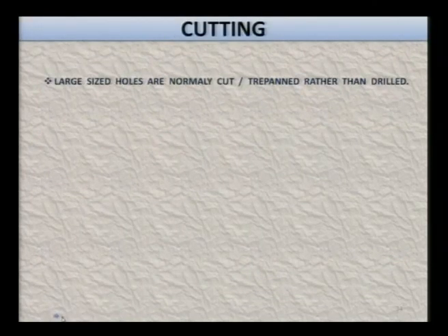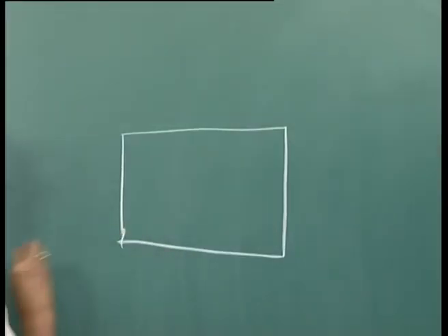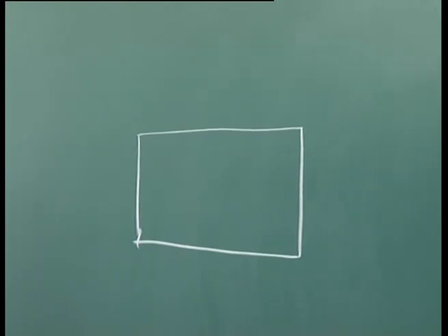Then there are various applications as long as cutting is concerned. Large sized holes are normally cut rather than drilled. This is a very important point. I will just explain to you here on the board that suppose this is a workpiece, and if you want to cut or drill a hole of around 1 millimeter, you can do it with the help of the laser beam directly. But suppose you want to drill a hole in a very hard material of around say 15 millimeter diameter like this,